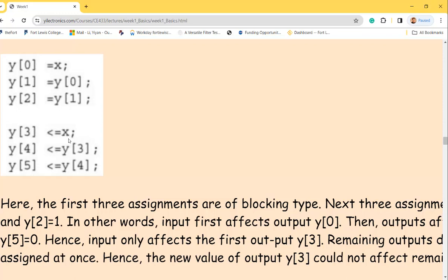But here is different. Keep in mind always, when you are writing Verilog, you are writing up a circuit instead of a programming language. It's not something being stored in the program memory and being executed one by one. It's being synthesized one time and it's not fabricated, but it's being implemented onto the circuit.